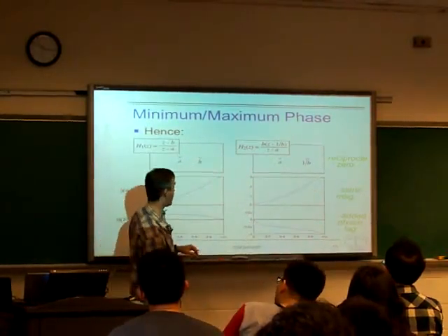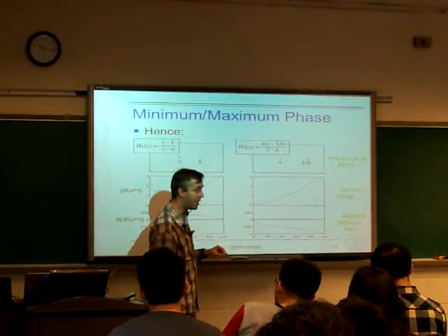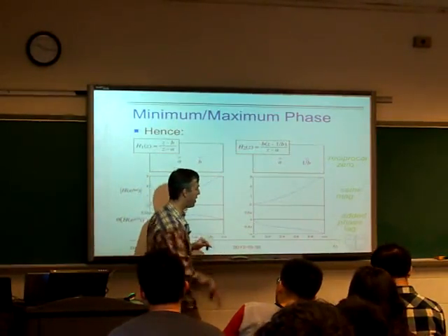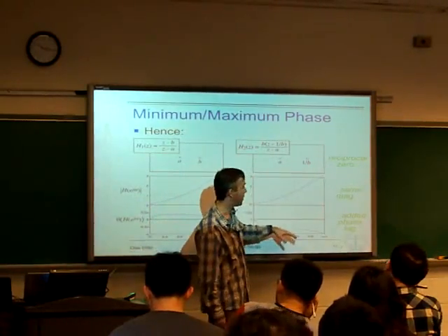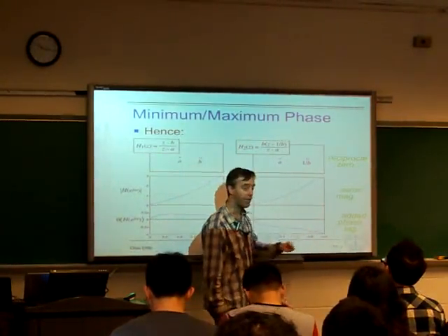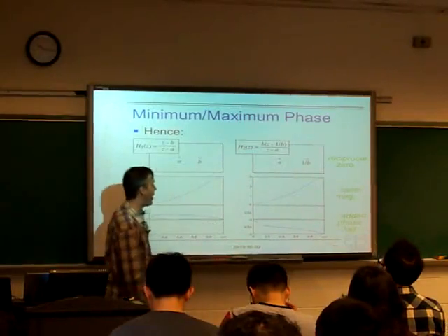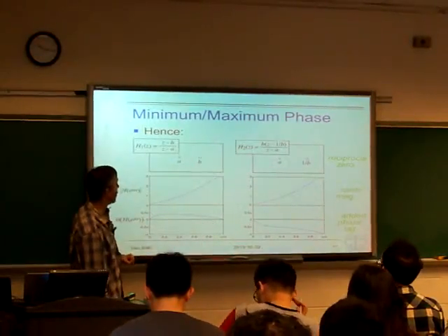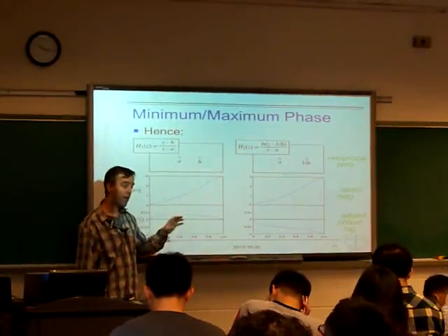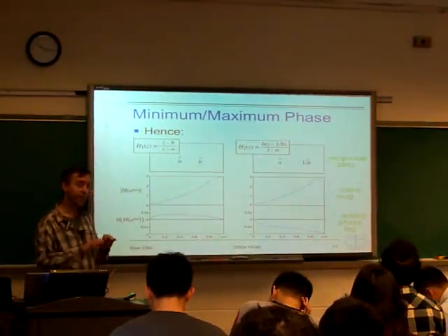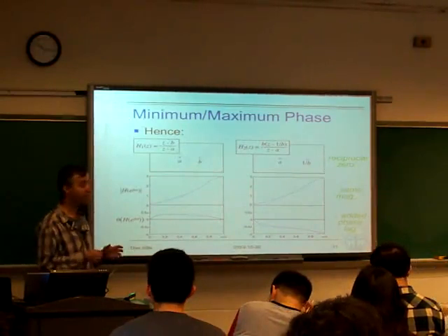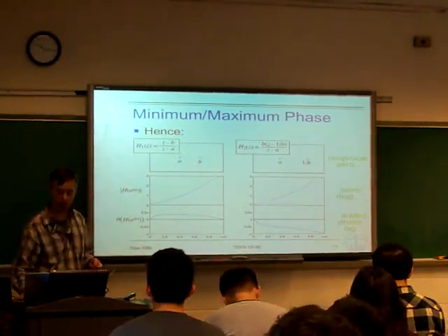And in fact, the phase response is less well behaved if we're shooting for a phase response close to 0, because it actually has this sort of phase that continues to experience more and more delay as frequency increases. So if we'd had more than one zero, we could have done this for each of the zeros individually and ended up with a whole series of filters, all with the same magnitude response, but each with a different phase response.